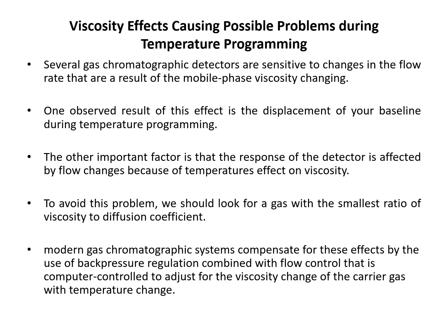Several gas chromatography detectors are very sensitive to changes in flow rate that result from changing mobile phase viscosity. The obvious result of these effects is the displacement of your baseline during temperature programming. Another factor is that the detector is affected by flow changes because of temperature's effects on viscosity. To avoid this problem, we should look for a gas with the smallest ratio of viscosity